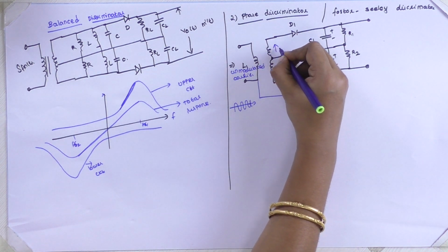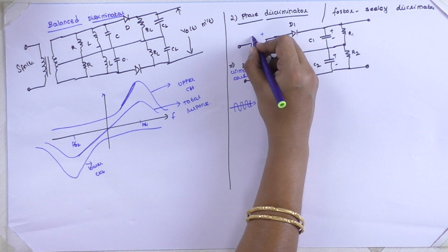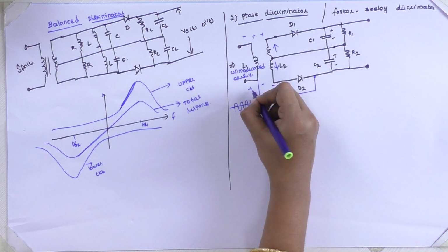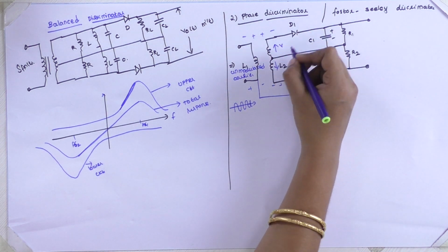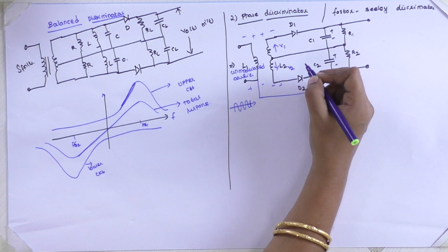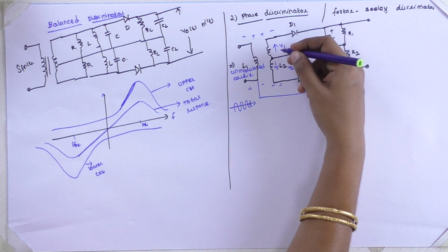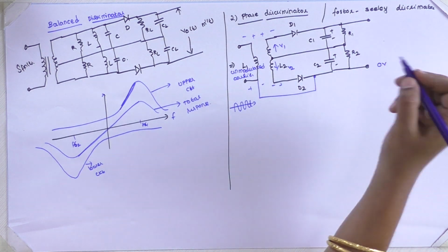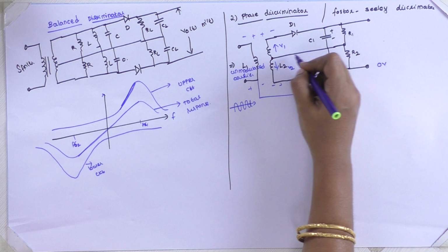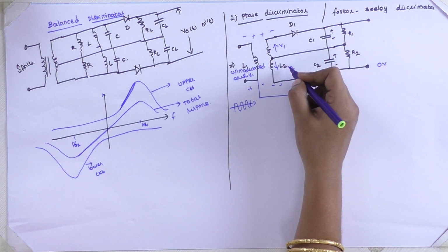Therefore, either plus and minus or minus and plus, our input voltages V1 and V2 of t will always be in antiphase. If we have antiphase, the output voltage will always be 0. This is a half wave rectifier and this is a half wave rectifier, fed to the center tap transformer.